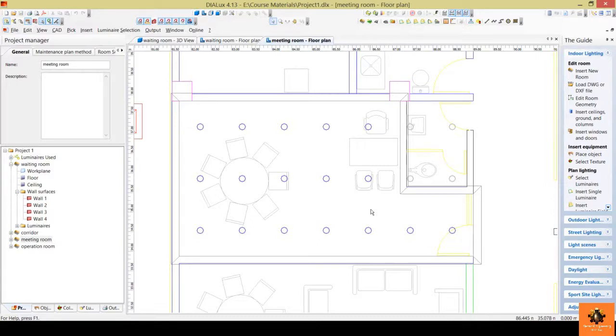And from here we come up with the idea of the emergency lighting, which is to select some of those luminaires which will be fed from 2 power sources at the same time. Hence, some of those luminaires will be used as emergency lighting luminaires, which means that we will feed them from 2 power sources.